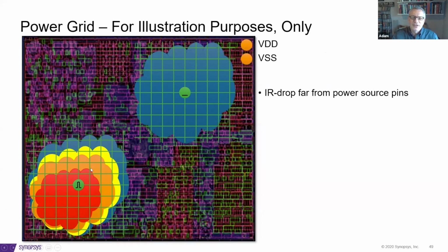So now all of a sudden, it's not just flip-flop switching necessarily. So that becomes a worse correlator, or not the best collection of data. We need to actually know about exact current profiles of the cells and even the parametrics of the mesh itself to draw some conclusions, or to drive the tools to do the right thing to avoid IR drop in different places.